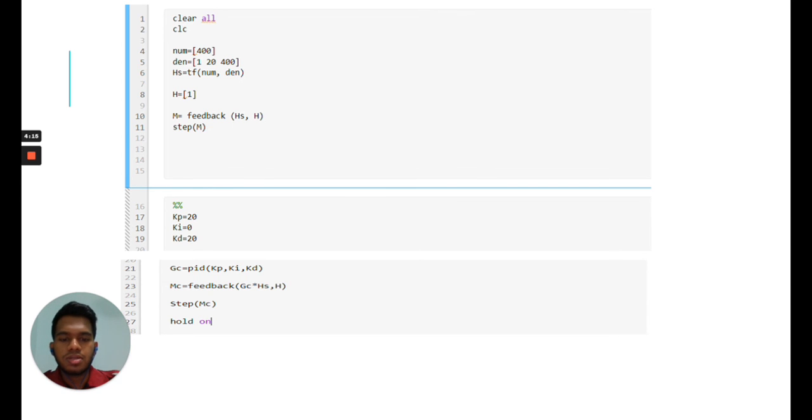Proportional integral derivative control, PID, is a feedback-based control loop mechanism that is widely used in industrial control systems and other applications that require continuously modulated control. So this is our coding for our PID control. This figure shows our PID control coding. As you can see there, from line 17 until 19, we input the values for KP, KI, and KD. So we keep changing them to get a better graph.